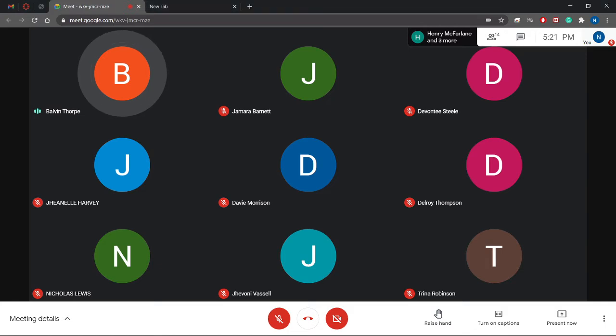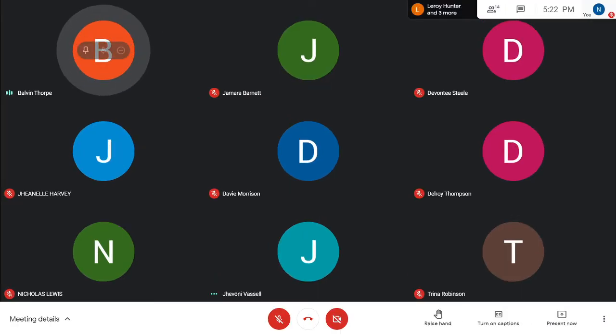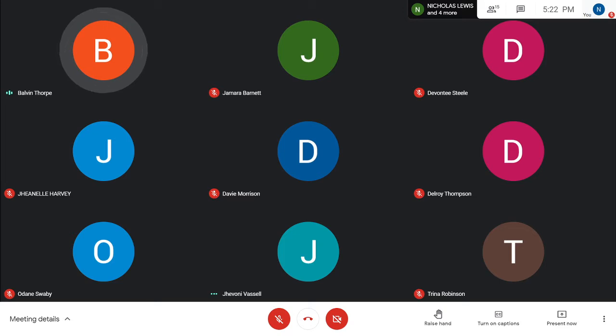Well, the current to voltage converter, I did mention it. It's a very simple circuit. I mentioned that you're applying current, and that current would be amplified. But because you have a resistor at the output of the amplifier, the current is going to go across it, which means that you can get voltage. Remember, anytime you have current flowing through a resistor, then voltage develops.